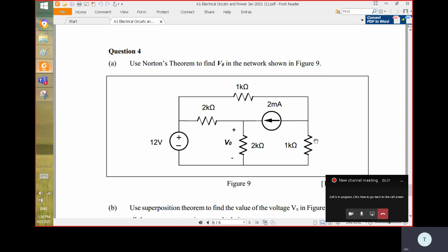but in this case right now, this is not our output here. Usually our output is at the right hand side, but for this question, the output is actually right at the center here. Okay, so this is our load actually. The 2K is our load. It's not considered part of the fixed circuit here. This is the fixed circuit here: 1, 2, 3, 4, 5. Not this 2K. This 2K is the RL, our external circuit. This is why we measure the V out here.